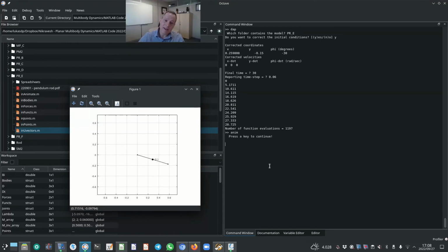Now we're applying a torque of 6 Newton meters, but we're specifying that the angular acceleration can only be 2 pi over 60 radians per second squared. So the simulation is calculating what I call a braking torque. It's braking the torque that we are applying in order to yield the prescribed angular rotation. And that's actually amazing that this algorithm is capable of doing that. I think it's amazing. If you don't believe me, I'll show you in a minute.